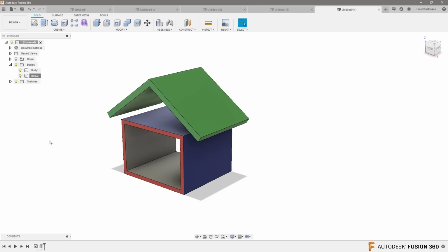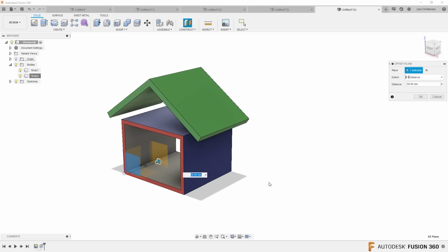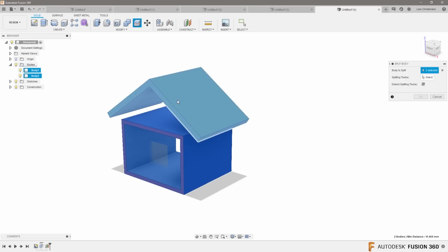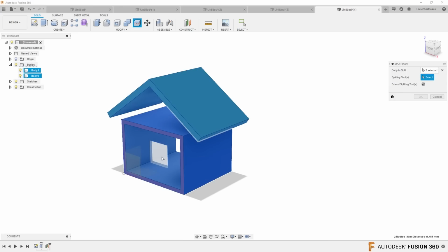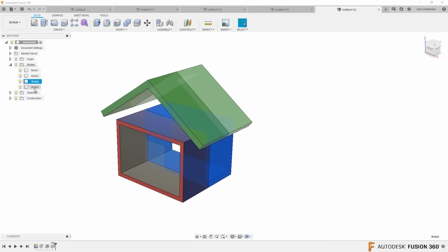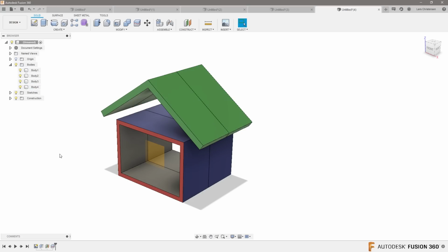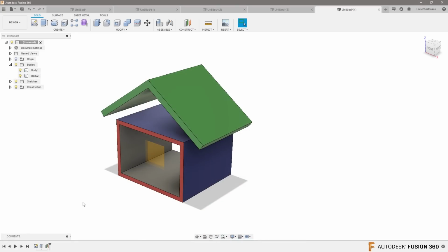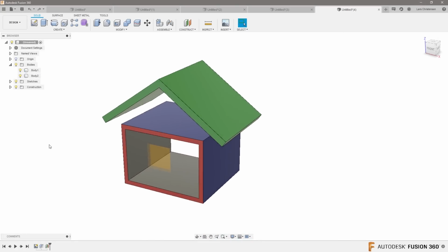We almost did that already early in the video with a piping scheme, but we could go in here and create an offset plane, cut that through there, and then split the bodies with that plane, and delete the bodies that we don't want to keep, and make a section like that. But when I'm looking at your drawing, we are looking at getting some notation in there, and that is probably where the 2D drawing environment starts becoming useful.